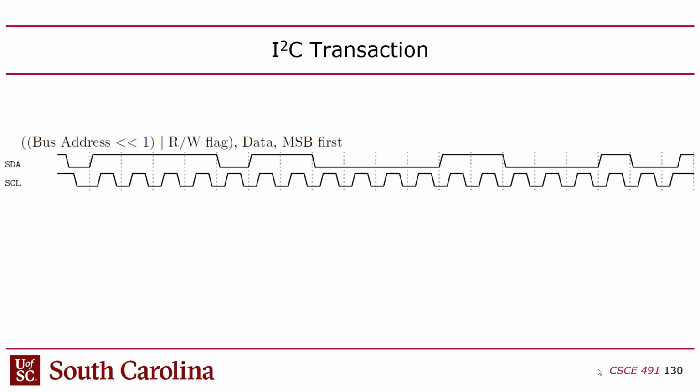0001, that's a 1, so it's 3, 1. And then the slave takes control again to acknowledge, and the acknowledge is a 0, which means we're good. And then we have the stop. What's the stop bit? Stop bit is clock goes high, data goes high, right?